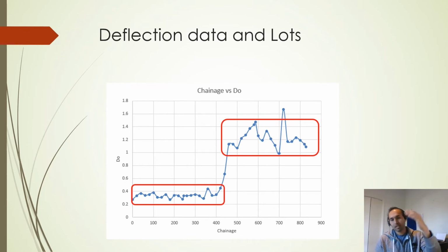So you've got high deflections, high subgrade rutting potentially, and you've got those low deflections, which while you've got cracking at the surface, indicates you've got asphalt fatigue happening, but you might not be getting that subgrade rutting down the bottom. And they might require different forms of treatment depending on how you could treat those areas.